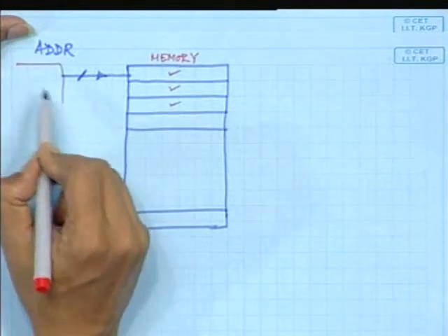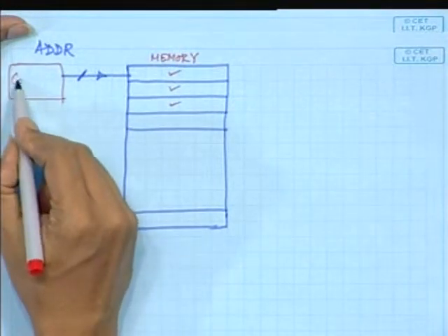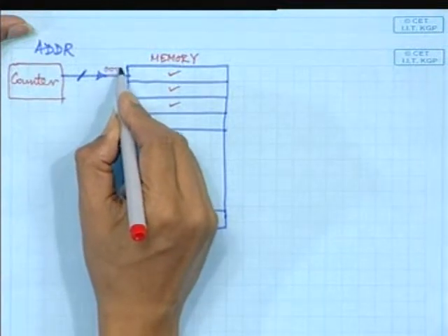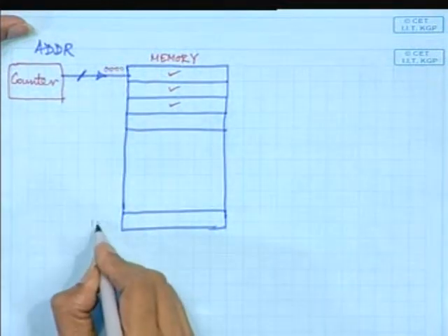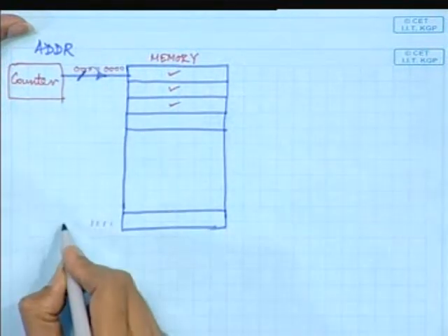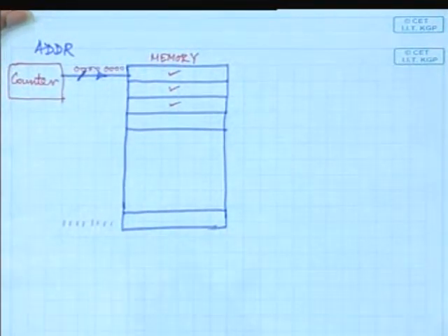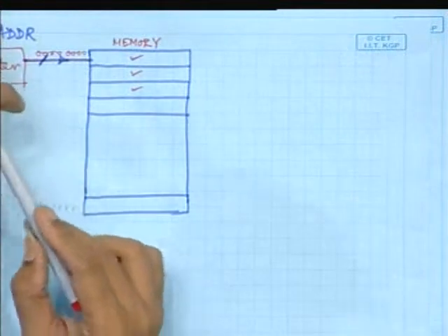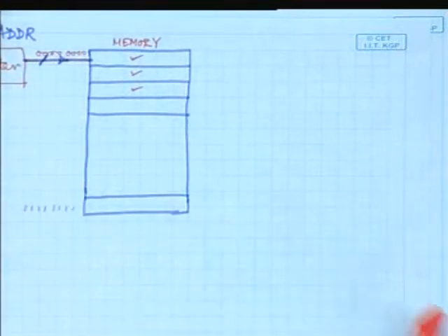So, effectively we are having some counter here that counts from 0 0 0 0 etc. to all ones. Okay. So, if it is 8 bit, we start with 8 zeros and gradually we will reach 8 ones. Okay. So, now whenever the counter outputs are changing, as we have seen that any change means power consumption, because capacitors are getting charged and eventually getting discharged.